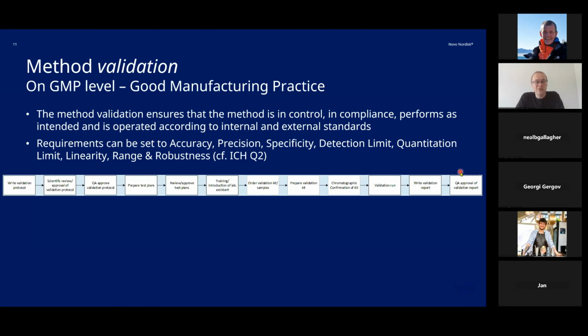So you could say that this is the final test set of a method, and you have no possibility of doing variable selection to fit your PAT measurements to the reference measurement at this stage. You have no possibility of changing components. You cannot change instrument settings and so on. You are validating the multivariate model along in this way. And then you can say that model is released, and you're good to go.